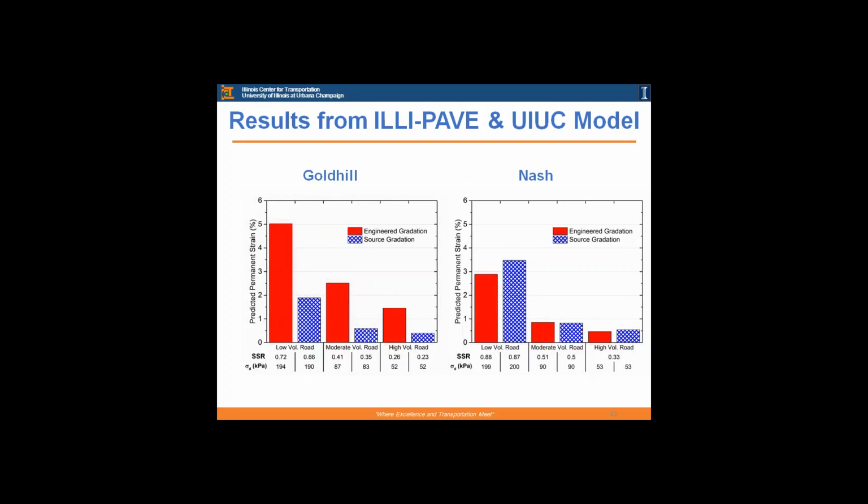Any other question? Yeah, the other thing is that we cannot measure the Poisson ratio of this material, you need to relate it to something. Poisson ratio? Yeah, that's really hard to measure for granular material in the lab. That's probably one of the reasons that both stress and strain need to be included in the models. That's a good comment. You always assume that number, right? Yeah, exactly. The number is going to be around 0.35 for unbound materials, but it's actually very hard to measure it.